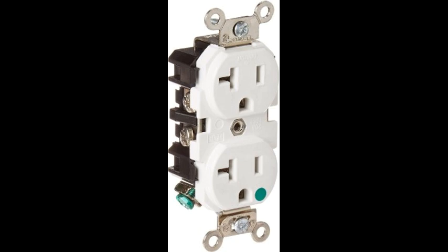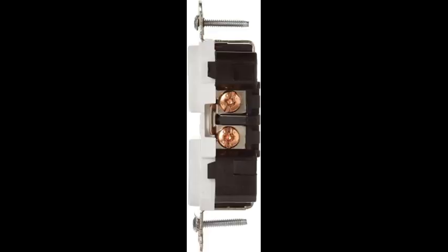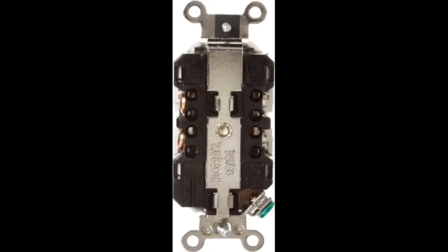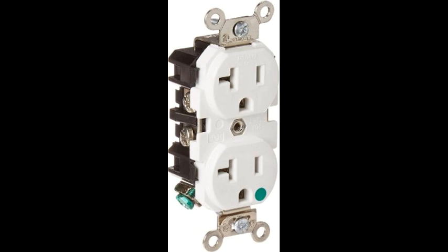The proper wiring for an AC outlet includes those 3 wires: black for hot, white for neutral, and green or bare wire for ground. The black wire connects to the brass screws, and the white wire connects to the silver screws, and the green or bare wire connects to the green screw terminal on the outlet, as shown in the photo. 14 gauge wire is appropriate for most 15 amp circuits. Wrap each wire around the appropriate screw in a clockwise direction.